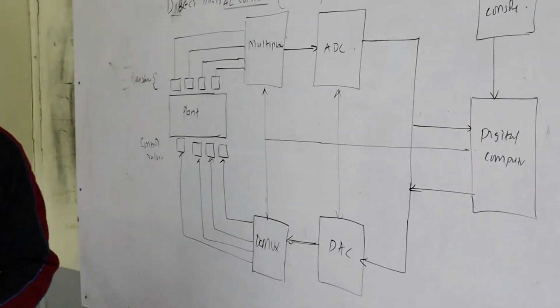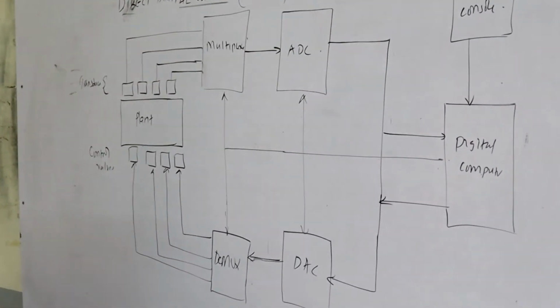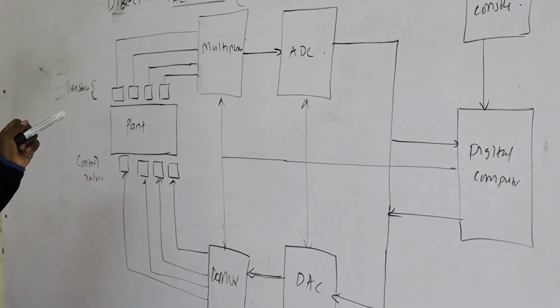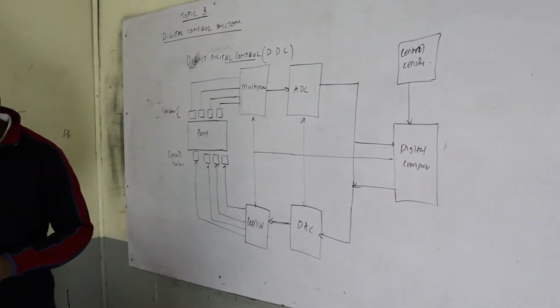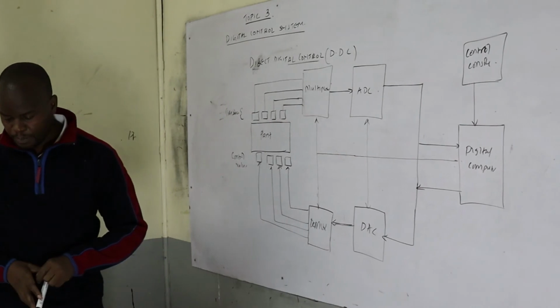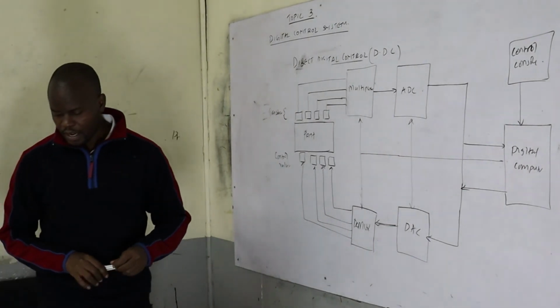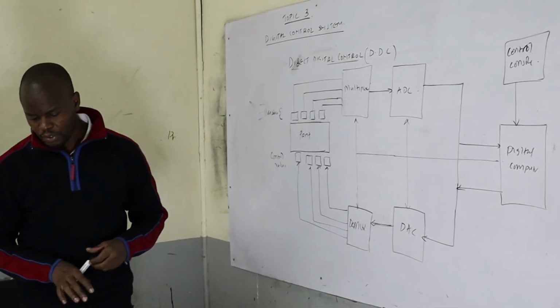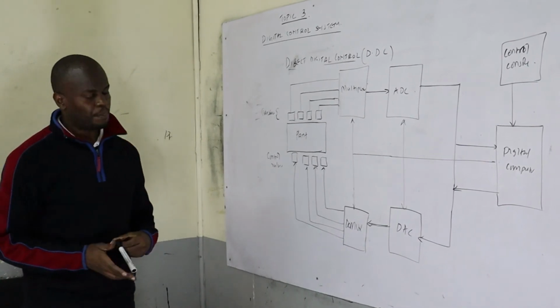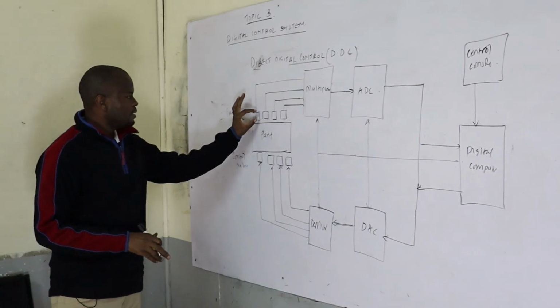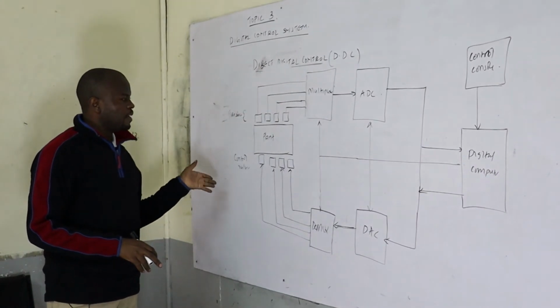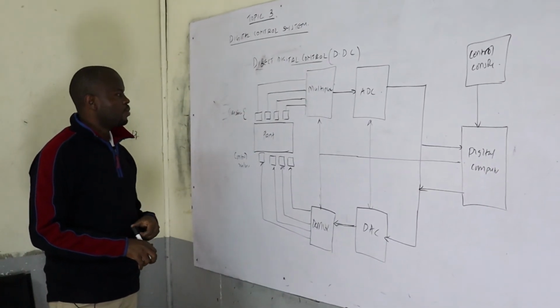So when we talk about this, we have several control valves and also several transducers. And in this case, when the CPU has analyzed the data from one or more transducers, then it has to compare with the appropriate set point. Each and every transducer represents the physical quantity that is supposed to be controlled.